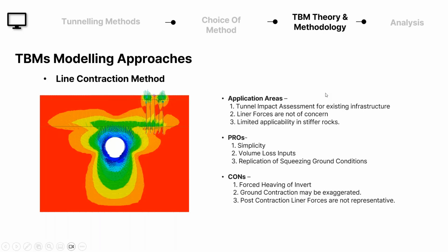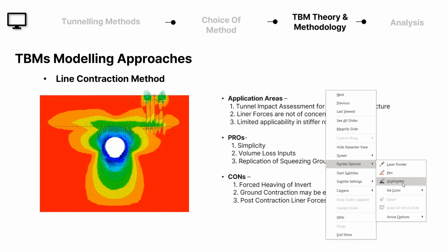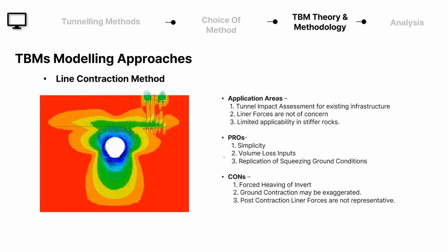the fact that you can actually assess this, which is the biggest concern, especially in urban areas, when you are executing a TBM tunnel where you have squeezing ground conditions. Because if the ground squeezes too much, there is a chance of the TBM getting stuck. And it has happened throughout the world that TBMs have gotten stuck. So this is a good assessment for taking note of these squeezing ground conditions.